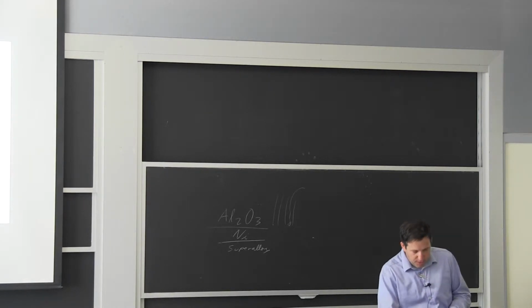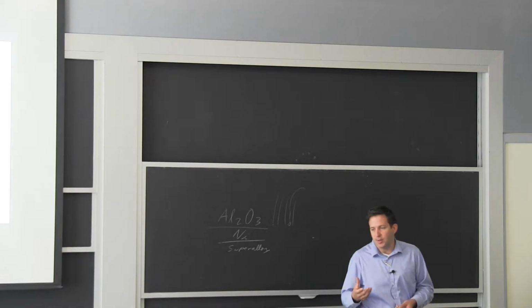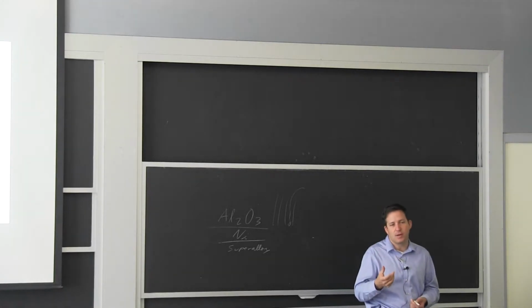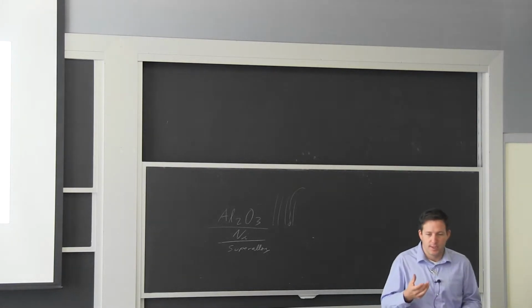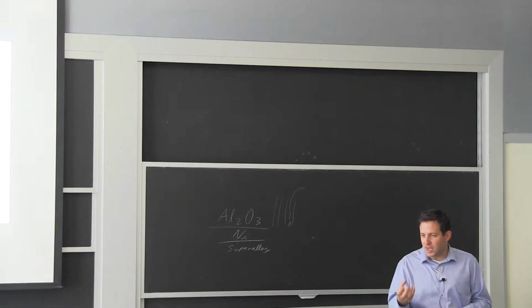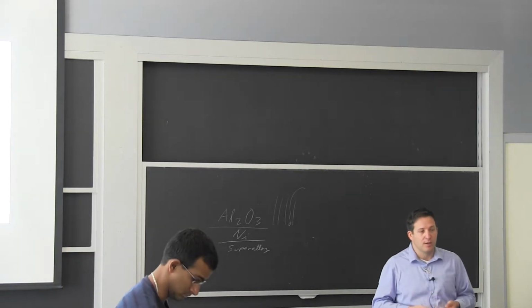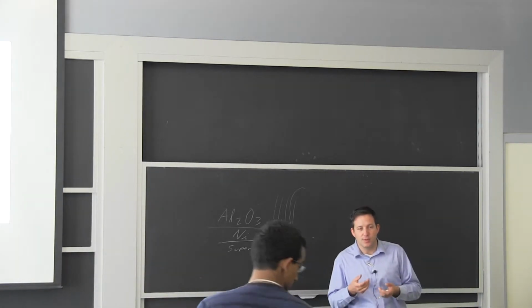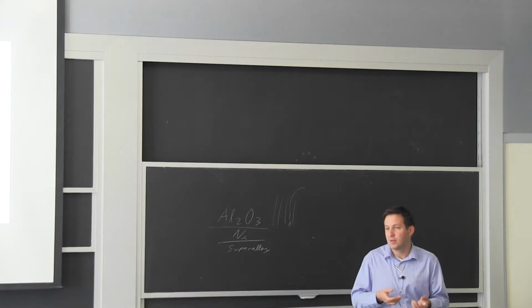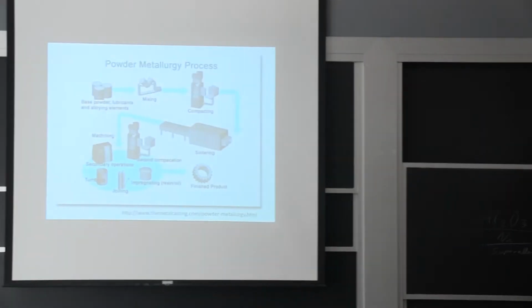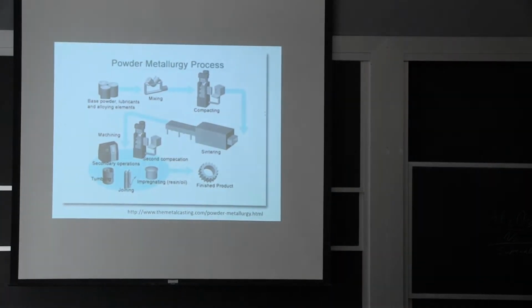A few other processes. We were talking about powder, and there are many industrial methods to make very fine powders. I can't get to the details, but you can make it very spherical by atomization typically, or you can go through a certain heat treatment method that will make it more flaky. If you look at cereals, you have iron added for health, and most of the time it comes from the same process that we also use to make parts.